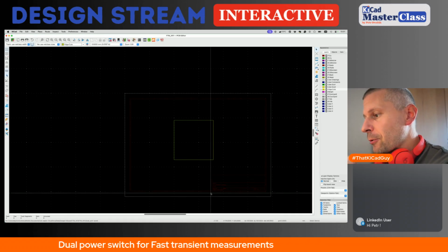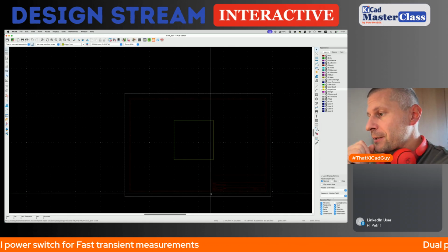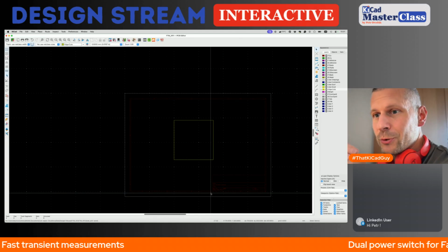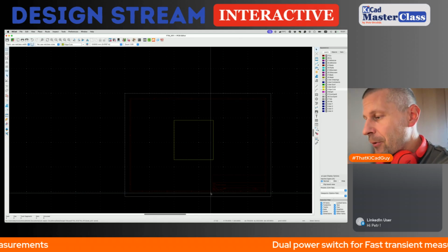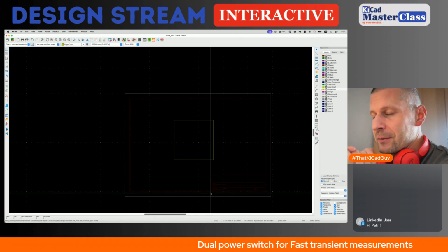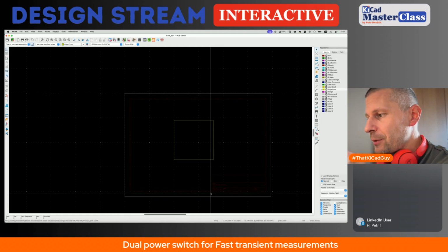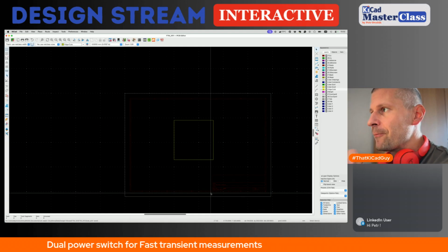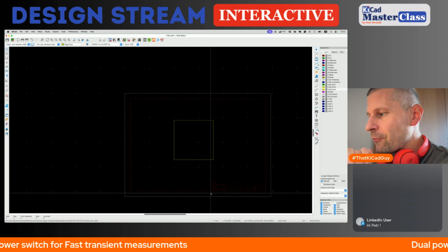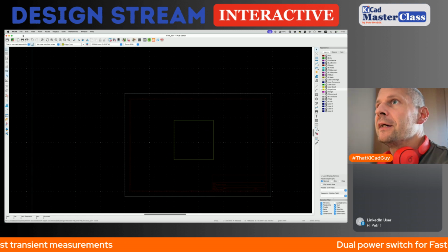Why? Because there are 3 power MOSFETs and I want to dedicate a reasonable and significant area on the PCB as a heatsink for these MOSFETs.